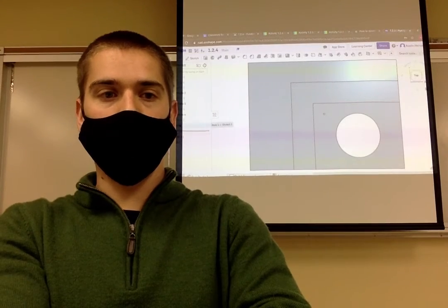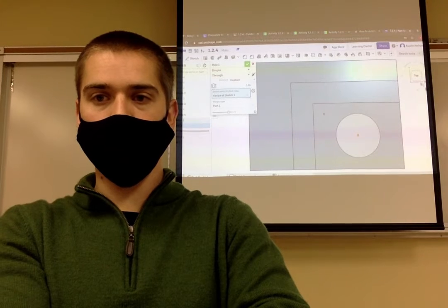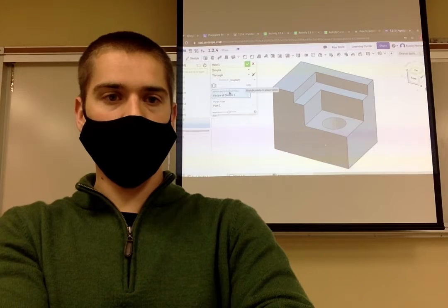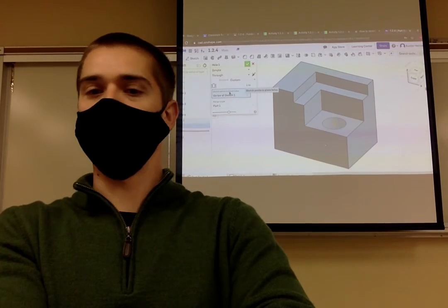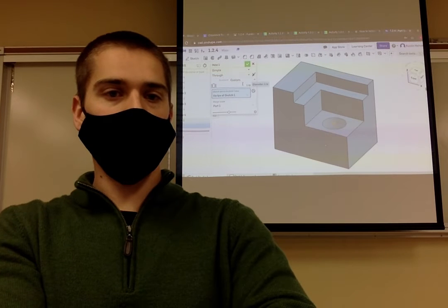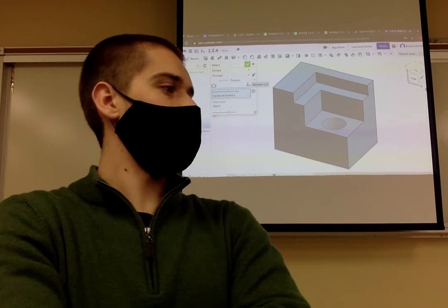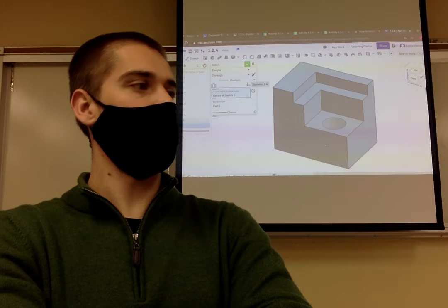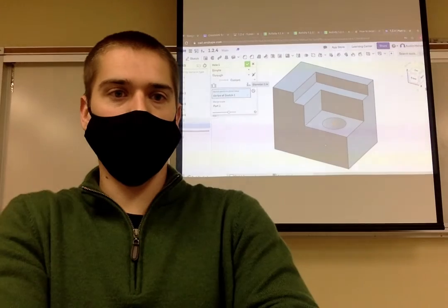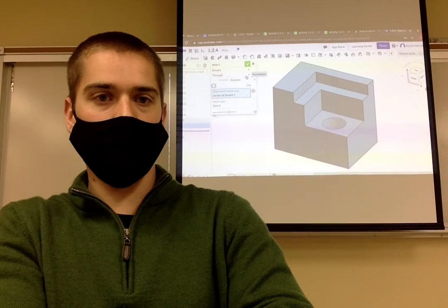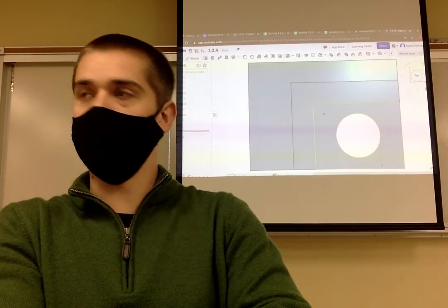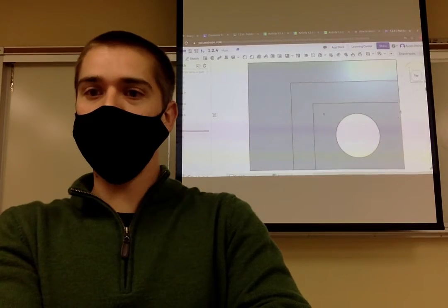Then, when I go to my hole feature, it prompts me to select the point to place the hole. I just drew it, so I just clicked the point I made. How big do you want your hole to be? Well, what was it dimensioned to be? It was right at 1 inch, wasn't it? So I just say it's a 1 inch diameter hole. It goes all the way through my object. Boom. There's my hole.